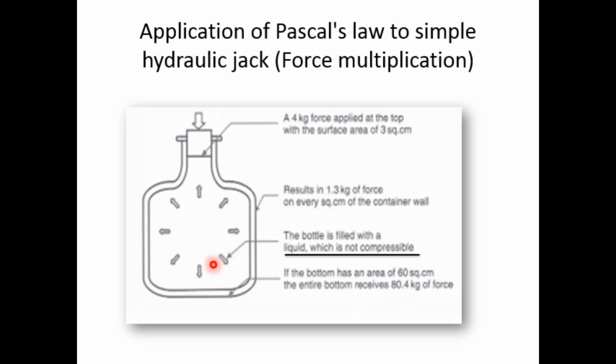That is the basic principle behind the working of any hydraulic system, and that basic principle was given by Pascal in his law, which is called Pascal's law. And what does Pascal's law tell? Pascal's law tells that force acting on a confined fluid is transmitted undiminished in all the directions throughout the fluid, and it acts perpendicular to the surface that is in contact with the fluid. You need to remember this law by heart, because it's a law, and law statements we are not supposed to change. Exactly what that law is, we need to remember and keep.